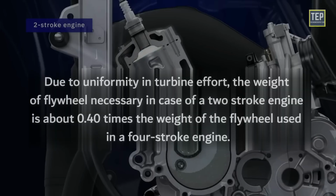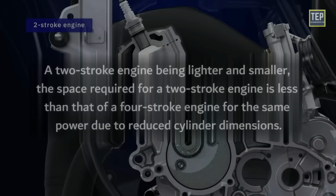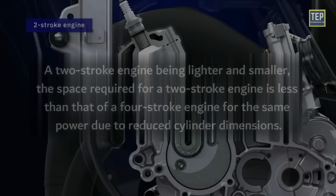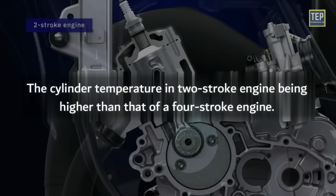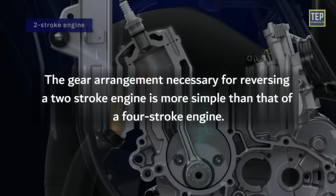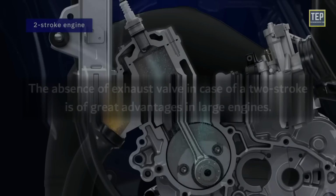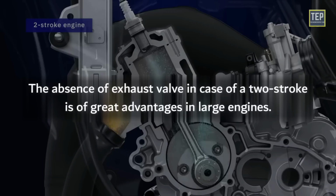Due to uniformity in turning effort, a lighter flywheel is necessary in the case of a two-stroke. It is about 0.40 times the weight of the flywheel used in a four-stroke engine. A two-stroke engine, being lighter and smaller, takes less space than a four-stroke engine for the same power due to reduced cylinder dimensions. The cylinder temperature in a two-stroke is higher than that of a four-stroke engine. The gear arrangement necessary for reversing a two-stroke engine is simpler than that of a four-stroke engine. The absence of an exhaust valve in a two-stroke engine is of great advantage in large engines.